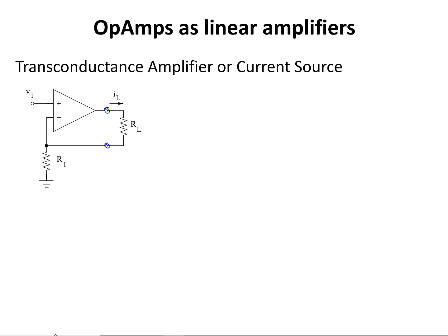So again, I'm going to use the first and second golden rule of op-amps. IN is almost equal to IP, that is equal to 0. I'm going to assume an ideal op-amp, also because there's negative feedback. There's this negative feedback network, and the output of the op-amp is connected through a resistive network to the inverting terminal of the op-amp. From there, Vn is going to be almost equal to Vp.